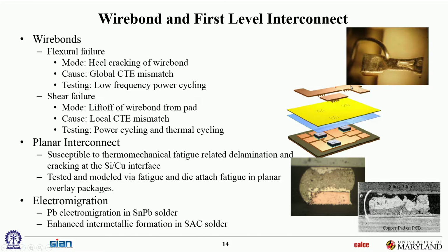So here you're putting these bus bars directly onto the chip without a wire bond interconnecting them. You have other direct contact mechanisms through vias and so on. So you use copper bus bars with vias directly on your interconnection points on your dies.